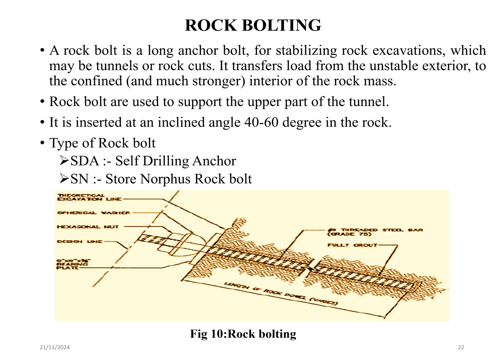Rock bolting. Rock bolts are systematically installed to further stabilize the tunnel. These bolts are inserted at an inclined angle into the rock and help to transfer the load from the unstable exterior to the stronger interior of the rock mass.